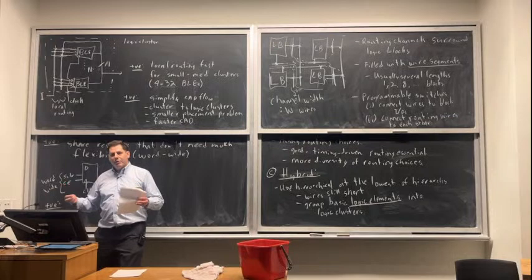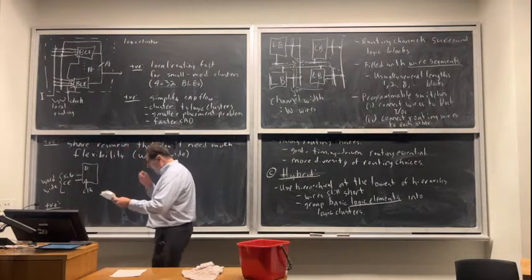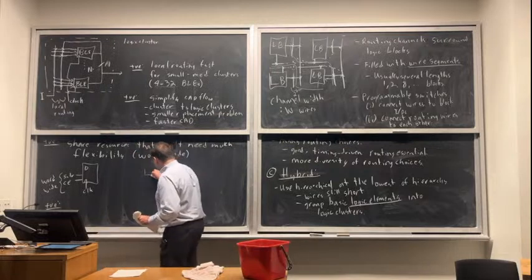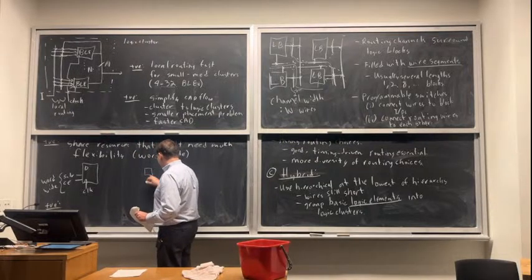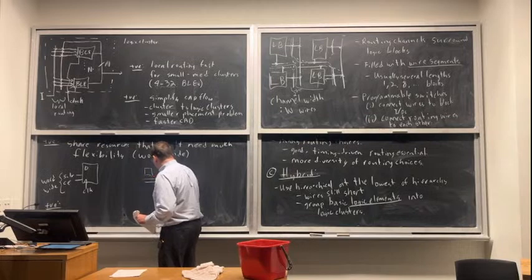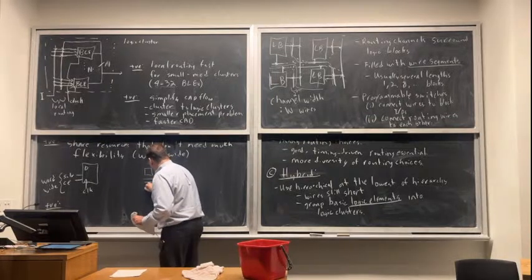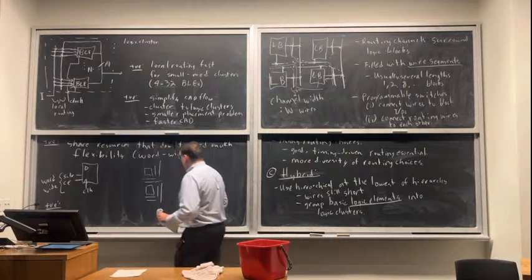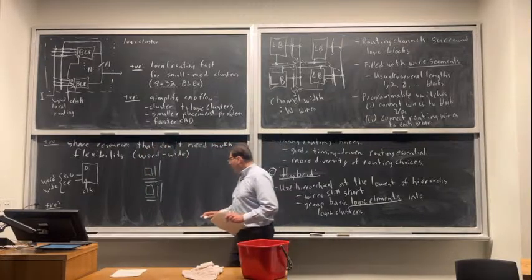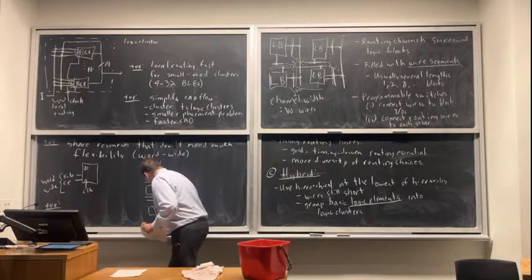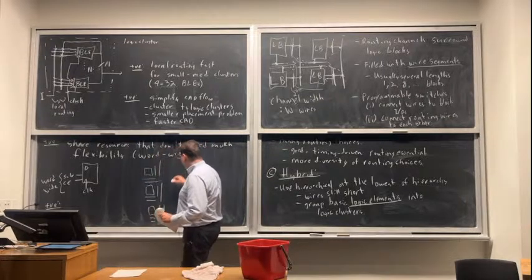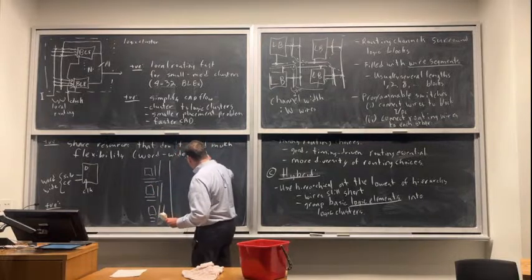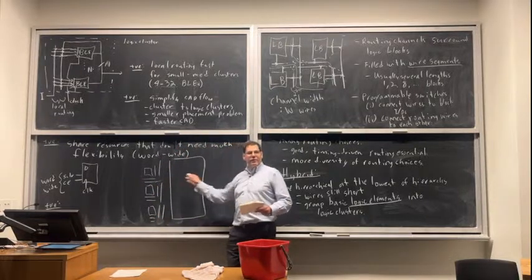Same thing if we do the same analysis for a DSP block. So if I was to take individual BLEs, individual LUTs, and put island-style routing around them, I can do that. It's got some downsides, like I just said. But then if I say, now at a certain column, I want to put a RAM block in, or a bunch of RAM blocks in, and the RAM block is like that, it's actually a lot harder to figure out how to make this routing work.